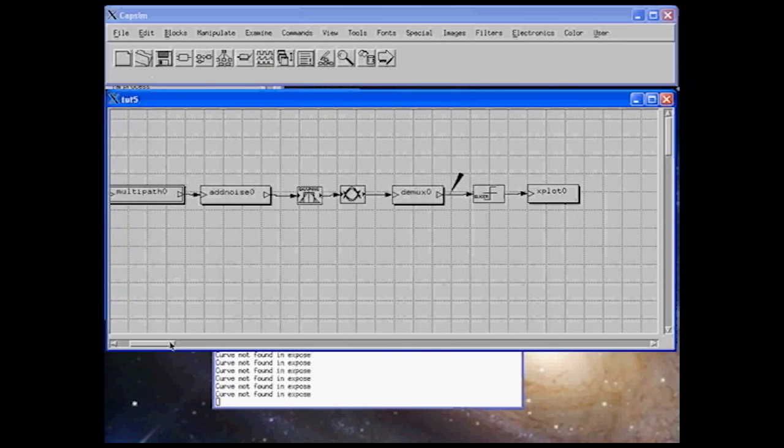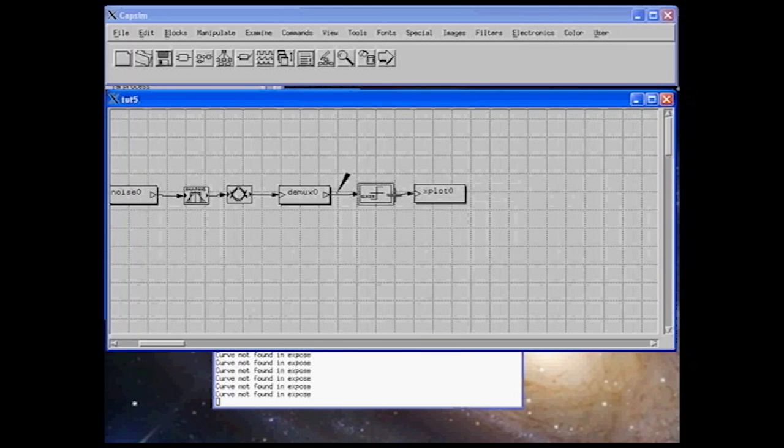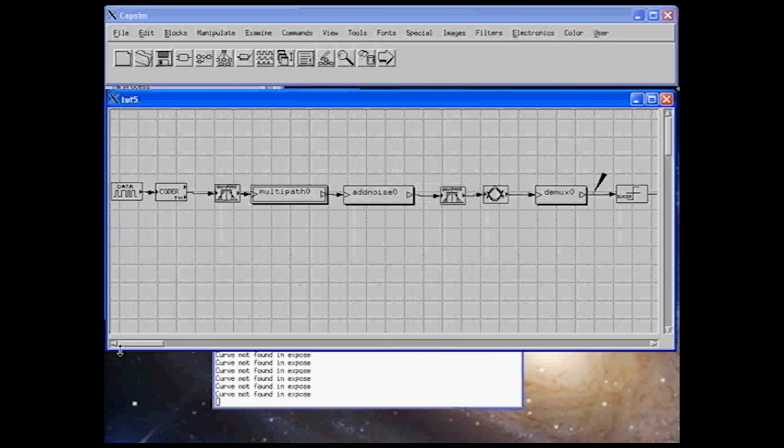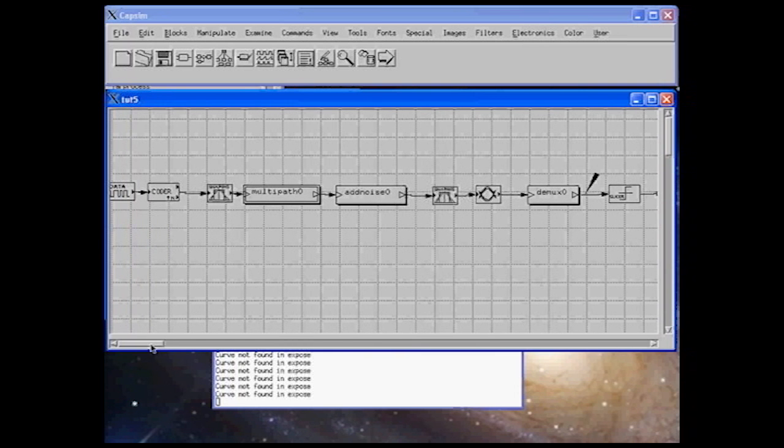Now the next step is to show how we can actually measure the bit error rate. After we do the decisions, the samples over here are estimates of the original bit stream that were sent. Now the bit streams themselves, although here they're binary data 0 and 1, the coder maps them to plus and minus 1. The slicer maps them also to plus and minus 1.